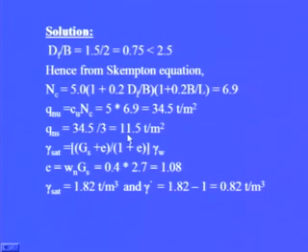Now in order to determine the overburden stress, we need to know the value of saturated unit weight of the soil. This saturated unit weight can be determined by the formula Gs plus E upon 1 plus E, whole multiplied by unit weight of water gamma W. Now this E can be determined for a saturated soil as water content into the specific gravity of soil solids.